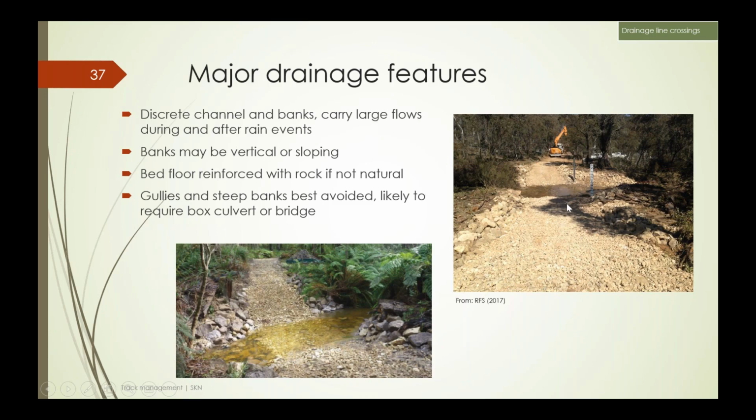But you can see here again, we've got an approach with a rock armoured run in and out, and then the water flows run across the reinforced bed. So that crossing is usable, perhaps not in a flood, obviously, but in most conditions, even though the creek is carrying water.